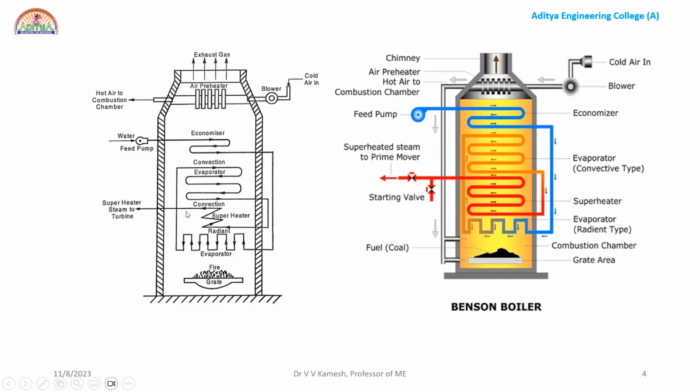So in between there are so many items. By the time the hot gases reach the economizer, some of the heat will be absorbed by the bottommost parts. So some heat will be there. Some of that heat will be taken by the economizer. So water will get heated, right? Water will get heated. Remember that point.